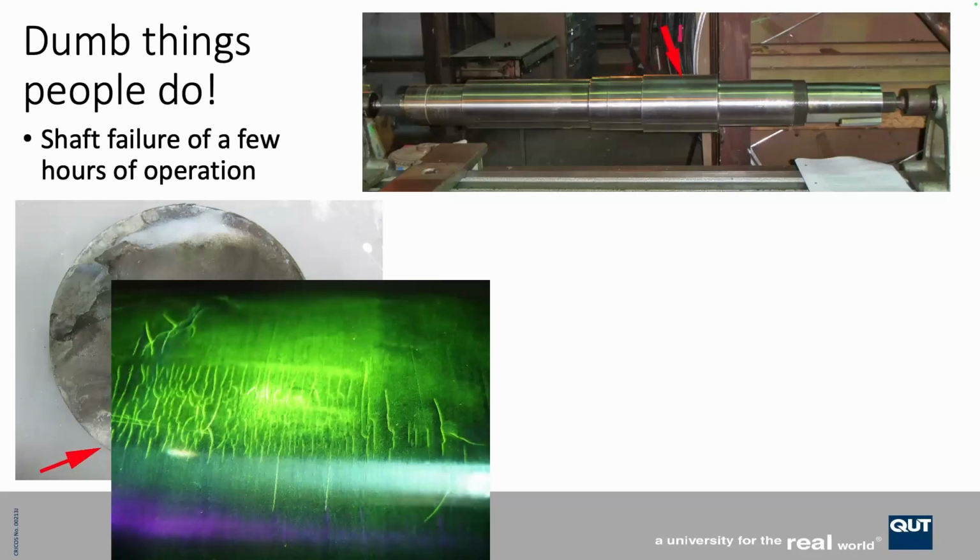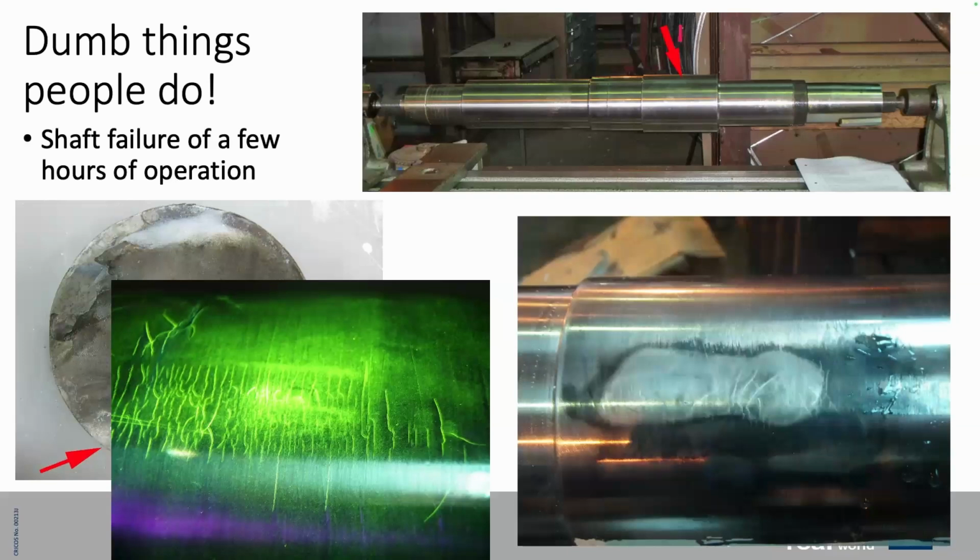What I did was, on this shaft here, which is one of several shafts, an intact shaft, we did some mag particle inspection in just this area and discovered the whole thing was cracked. And then I did a little bit of differential etching and found a large patch of white etching material here, and it was associated with the cracking.